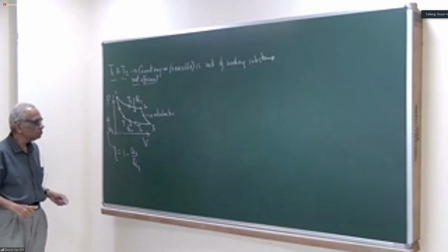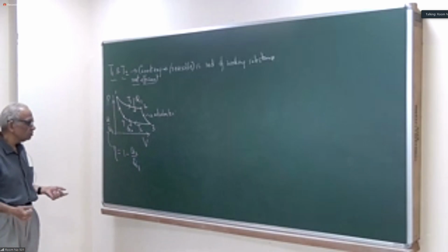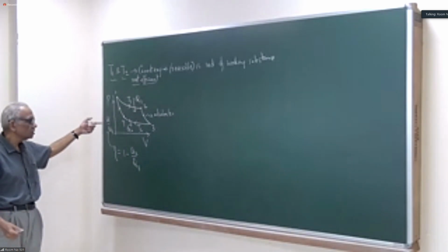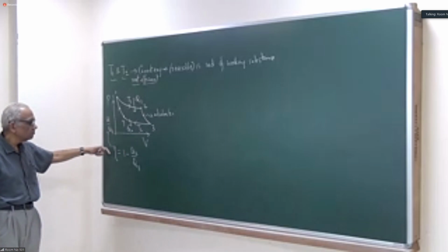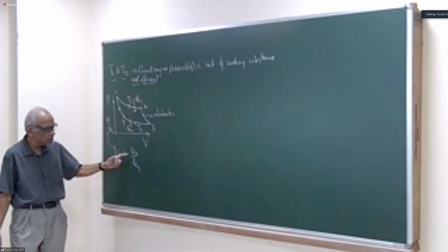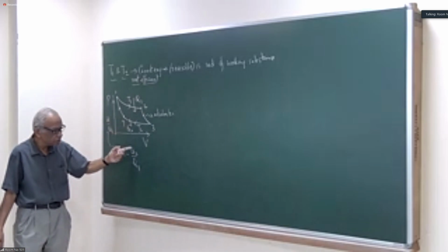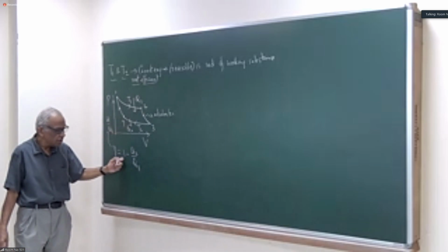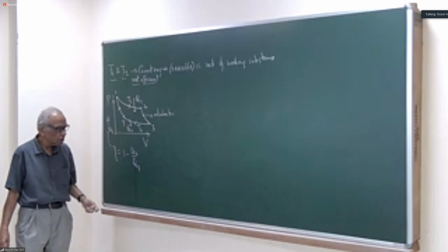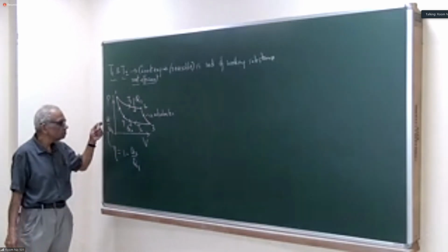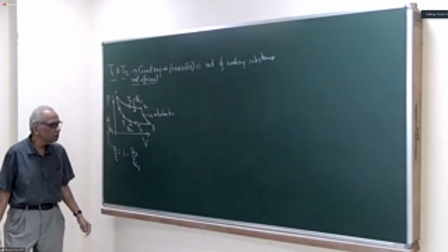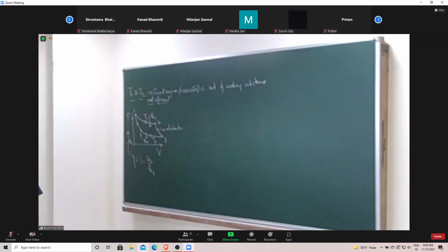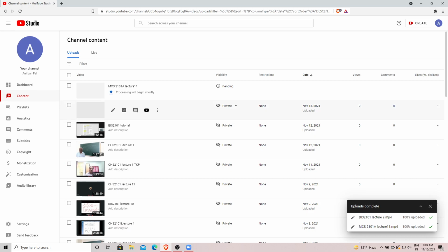It takes in this amount of heat, and can't convert all of it to work according to the second law, and therefore the work done is less than Q1. The efficiency is less than unity, determined by how much heat has to be rejected by the system. And so it is 1 minus Q2 over Q1. W is Q1 minus Q2, the total work done over the cycle.